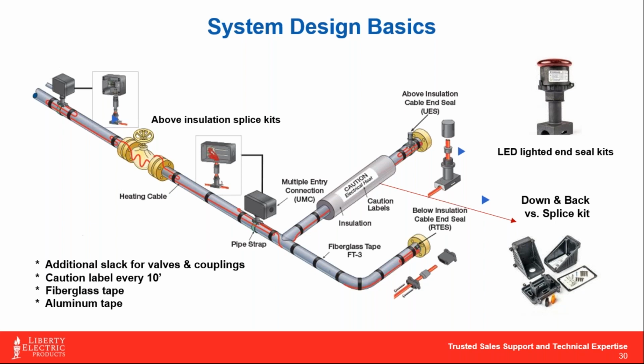I say that with a little bit of, let's say, bias towards the fact that, again, you need to know in some respects, like you don't ever put a double run, even if you're low temp self-regulating cable, on, say, a plastic PVC pipe. If it's a metal-based pipe, you can do that, and that's no big deal.